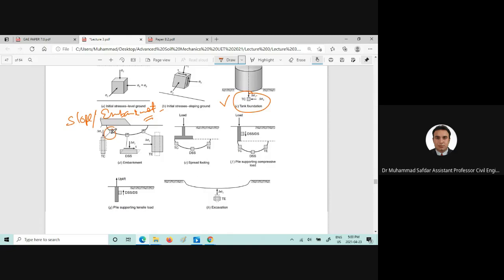For example, the triaxial compression condition, direct shear test condition, or the triaxial extension condition, and how along the different slip planes beneath the foundations, different types of tests can be used to get the required shear strength parameters.